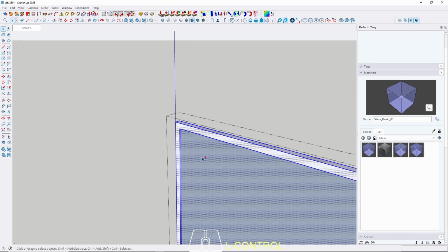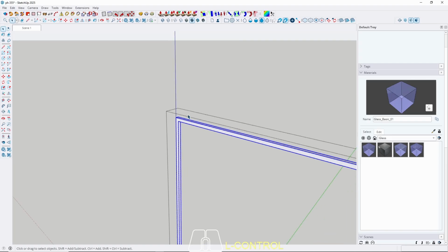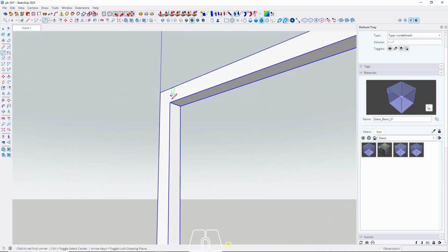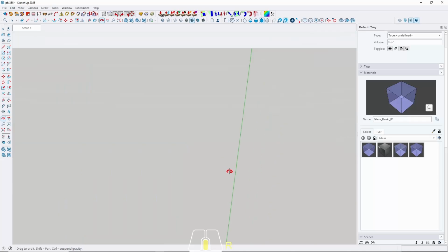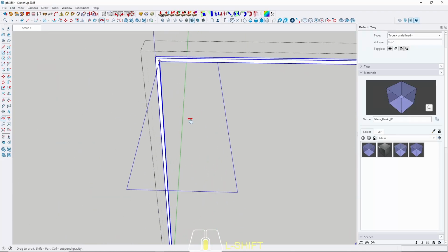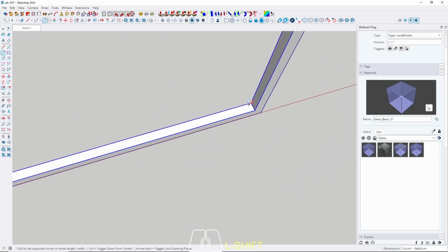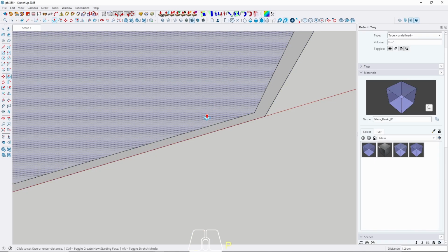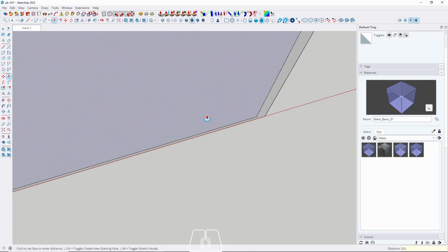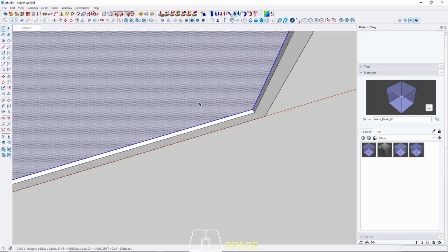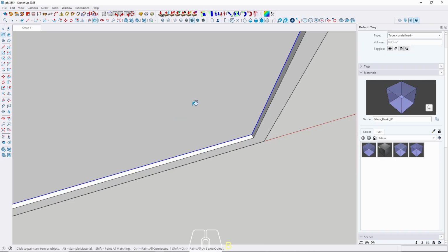It's very important to make a thickness on the door because it will affect the rendering result. So we have to be aware of the detail in your design. Like this, and make a thickness at least 0.5. Make it group and then apply the glass material.